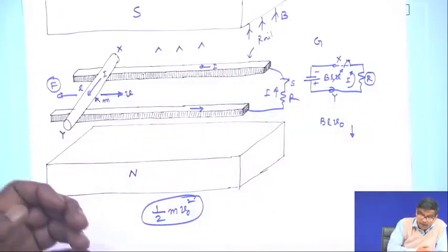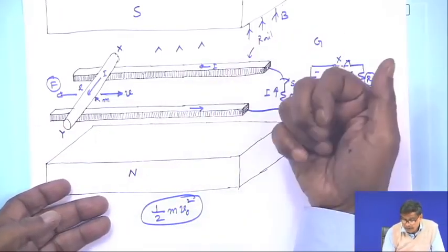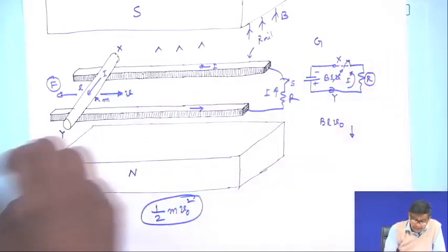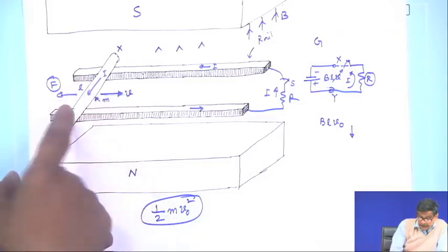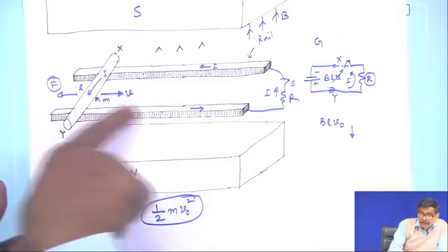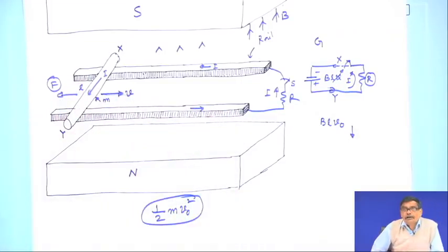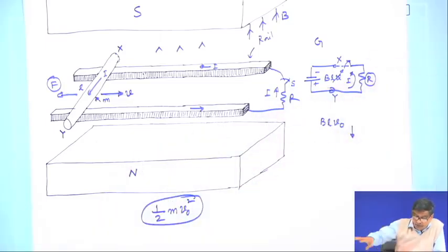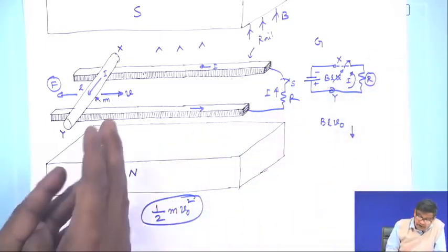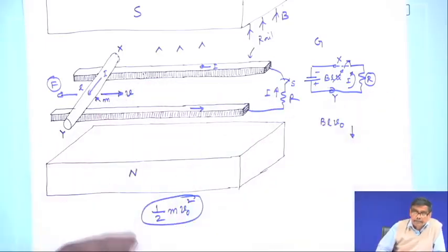And this is how to get electrical power: mechanically you have to do some work. That is why that forward force is to be applied, and that is called a prime mover in a rotating machine. You load the machine, then your mechanical supporting system must react to that and exert force or torque, so that velocity is retained.